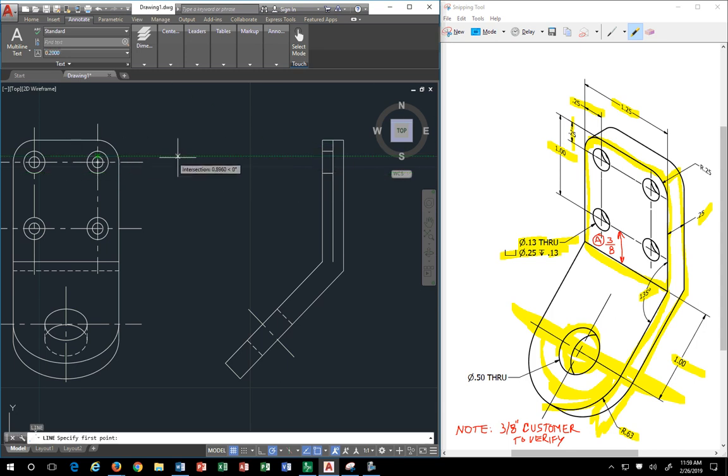Once you have the first one built, then you can complete the second one with relative ease, because you can always copy it down from this end point to the reference of those two points. See that? And then you can use the trim command, pick everything, so you can just lob off the elements of that line that you don't want.